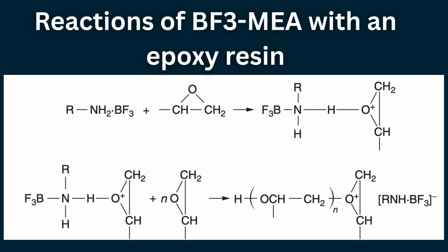Boron trifluoride monoethylamine, BF3-MEA. BF3-MEA is a Lewis acid catalyst formed from boron trifluoride and monoethylamine. It behaves as a latent catalyst because the amine moderates the reactivity of the boron trifluoride. Epoxy formulations containing 2 to 4 pph BF3-MEA can remain stable for months at room temperature. Significant curing activity begins only when temperatures reach 100 to 125 degrees Celsius. After curing, the resulting polymers exhibit dense cross-linking and excellent high-temperature mechanical properties.